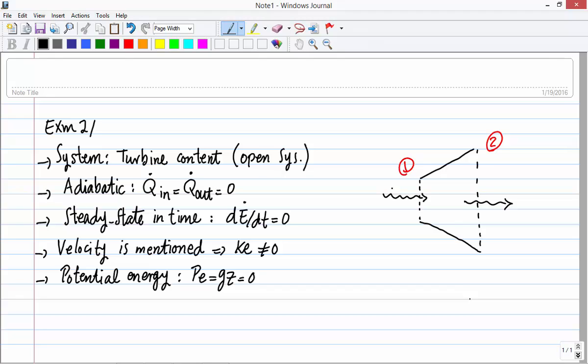So here is m dot in and m dot out, and there is no leakage or any external or separate outlet, so mass is conserved. So m dot in should equal m dot out, and I'm going to mention that in future. And also there would be E dot in carried by the mass going into the system, and E dot out leaving the system as well carried by mass, because I am drawing these arrows across this imaginary boundary, which means this energy rate is related to mass flow. So it has to be carried by mass.